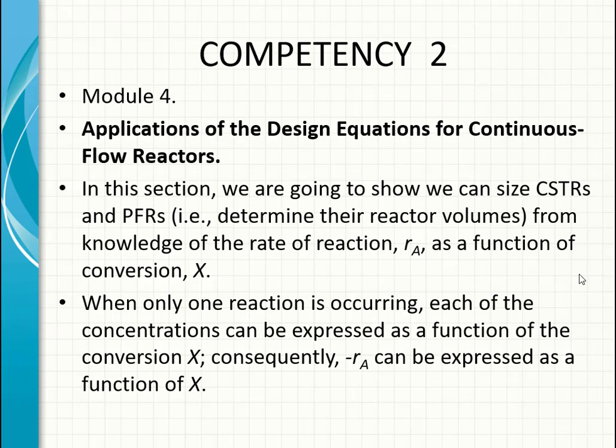Applications of the design equations for continuous flow reactors. In this section, we are going to show that we can size CSTRs and PFRs, that means determine the reactor volumes, from knowledge of the rate of reaction -Ra as a function of conversion.